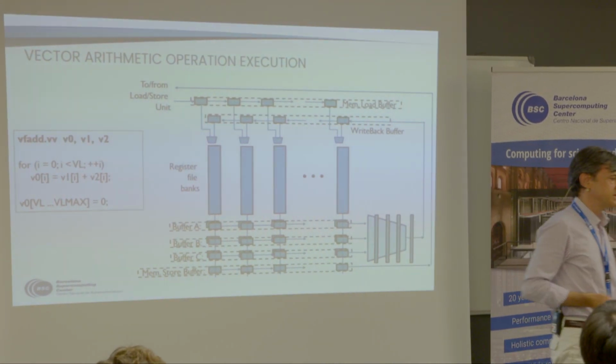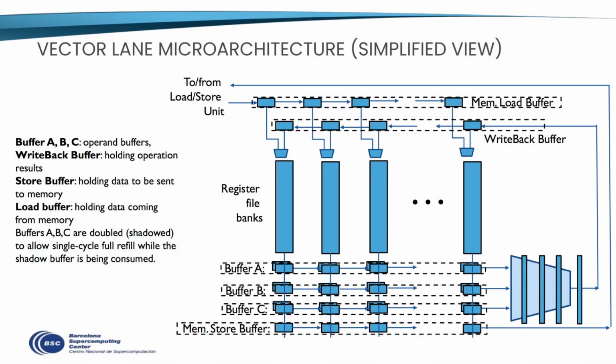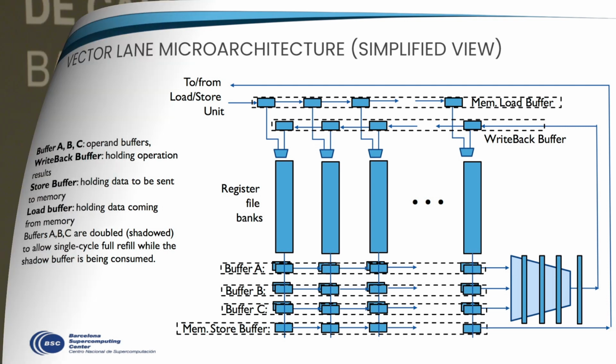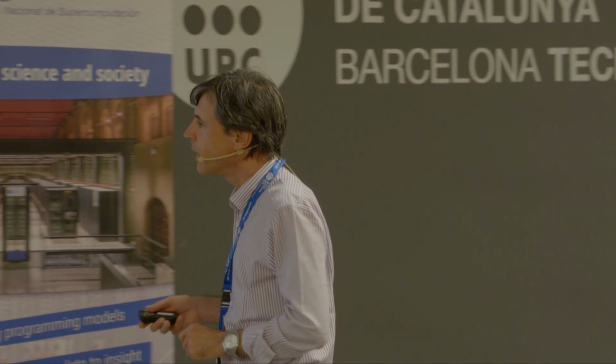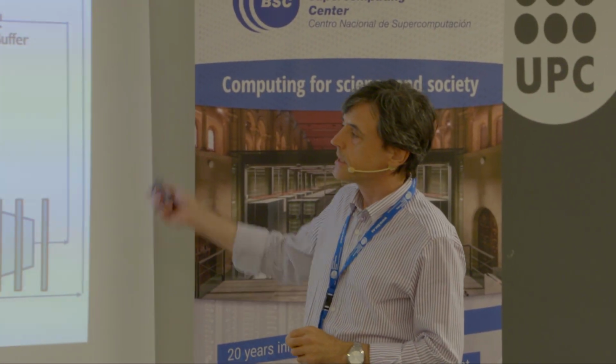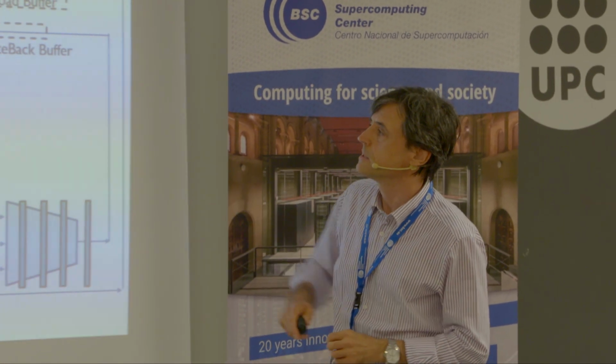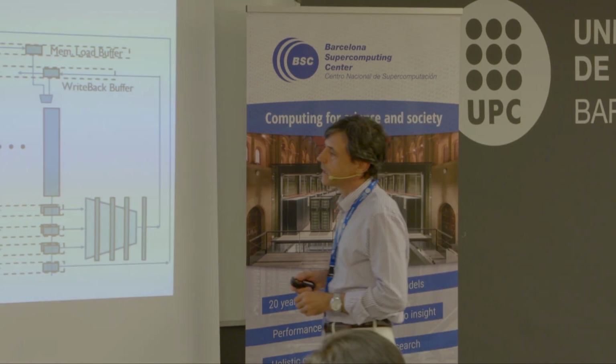For those of you who are interested in implementation, there is a debate about implementing these with SRAM macros or with standard cell-based register file banks. This depends on the size. It is a discussion that we may have if you want. We are still exploring this part. But the RTL design of all these things is ready and working anyway.